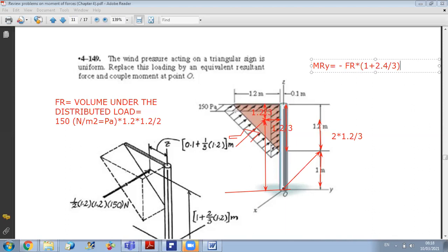Is my force producing a moment about z here? Yes. Okay, and is this moment positive or negative? Negative. Exactly, negative, because if I do the right hand rule, I put now my four fingers parallel to the force and the palm of my hand facing z. So if I put my hand like this, my thumb will point downward. So this is a negative moment, and I should multiply the force by which distance?